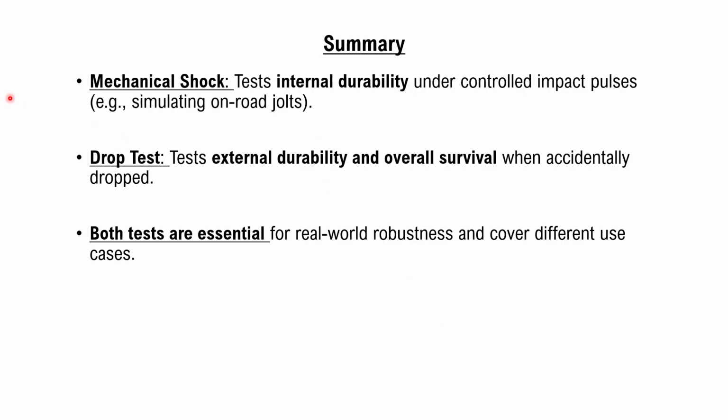Summary: the mechanical shock test checks internal durability during controlled impact pulses, for example, simulating on-road jolts, and the drop test checks external durability and overall survival when accidentally dropped. Both tests are essential for real-world robustness and cover different use cases.